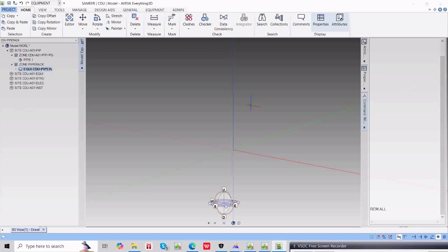After this, the structural people will do their own calculation, like calculating the point loads at every section, and accordingly they will create the structure. They are going to decide the size of the profiles, like the columns and the beams which they are using. So as a piping designer, your responsibility is to provide the layout for the pipe rack.